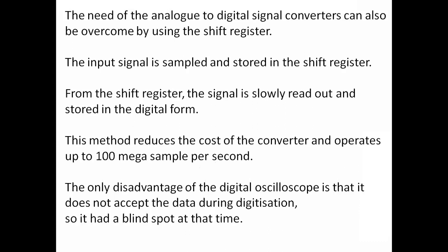That is the only disadvantage of the digital storage oscilloscope. While performing the digitization, it does not respond to or accept the input data. After the digitization is done, it will receive the data.